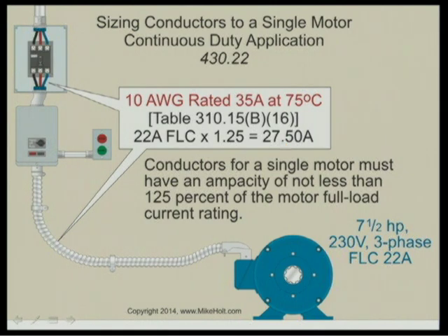And then if I remember right, it was 110.14(C)(1). Ryan, double check me. I don't know if it's C1B that says that motors under 100 amperes, is it C1B? C1A4. Oh, yeah, A. Like I say, C1, because 60 degrees C is A. 110.14(C)(1)(a)(4) says that motors are sized to 75 degrees C. So if the motor is 75 degrees C equipment and the breaker is 75 degrees C, then I would just go to Table 310.15(B)(16), go to the 75 degrees C column.